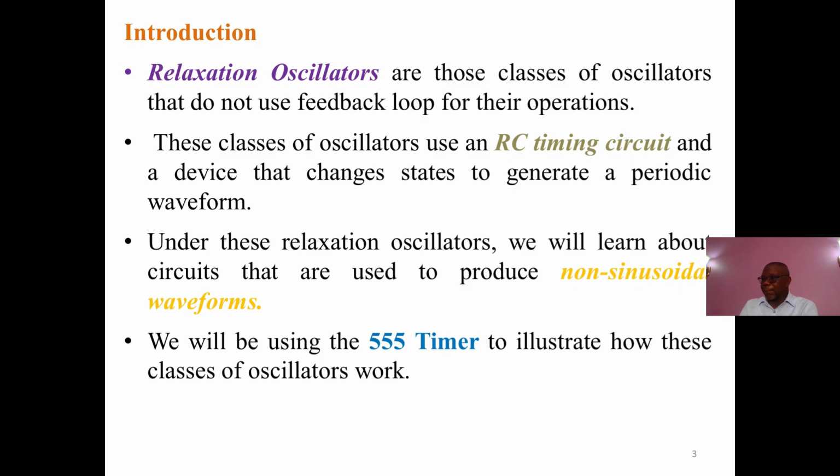Like we introduced the topic, our topic today is relaxation oscillators. So what class of oscillators are known as relaxation oscillators? We say that they are those oscillators that do not use feedback loop for their operations. These classes of oscillators use an RC timing circuit and a device that changes states to generate a periodic waveform.